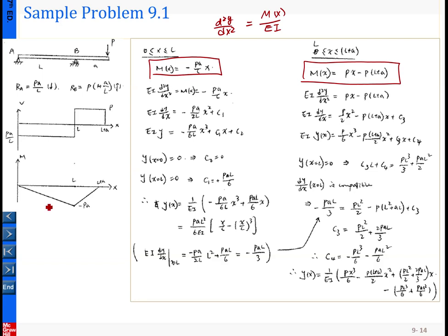So here, this piece is minus P over 2 times x, and for this piece it is Px minus PL plus a. That is the major effort you have to spend first. Again, you can look at our chapter 5 contents, and there are quite a few exercises there already.